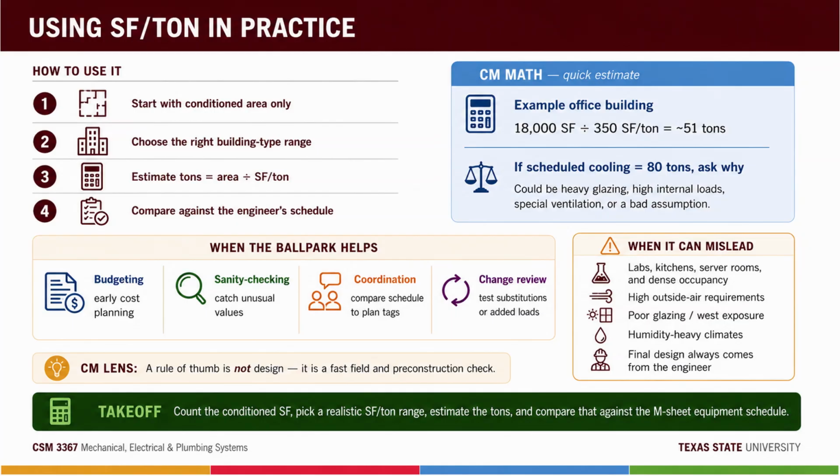Notice that number. The moisture load of the outdoor air just beat its temperature load. That's Gulf climate HVAC in one comparison. And it's why humid climate engineers obsess over outdoor air, energy recovery wheels, and dedicated outdoor air systems, while their Arizona counterparts barely think about grains at all.